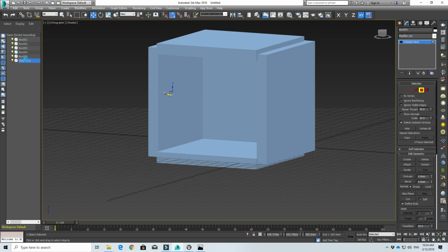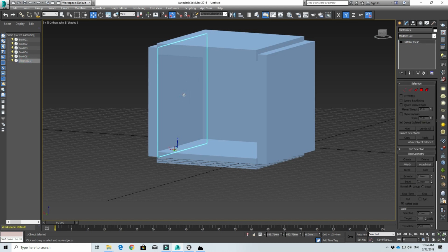So by detaching this wall, what we are doing is, number one, we are only giving focus to the important objects, to the important meshes, and we are reducing our building time. And when we import a plane like that, the entire light map is given to that plane, so this is the most efficient method to do a light map. Of course, we'll just focus on these huge areas, like the walls and the floors. Small things like the furniture, I think we don't have to spend too much effort. So the next step for our project is to start detaching the inner walls to form a mesh by itself, so that the light map will be optimized.